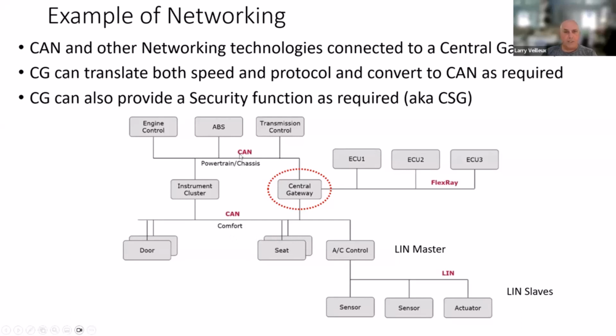And by the way, the reason for different CAN buses, in addition to that, this one in this case talks about a network for all your comfort interior items for controlling them. There's a separate one for the powertrain operation and so on, which could include braking, all that kind of stuff. And what you could end up with, and you'll see that in just a moment, is that different CANs can operate at different rates, both in terms of the speed that they operate, as well as the size of the data that they can carry and that sort of thing.